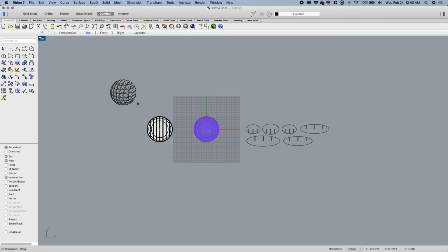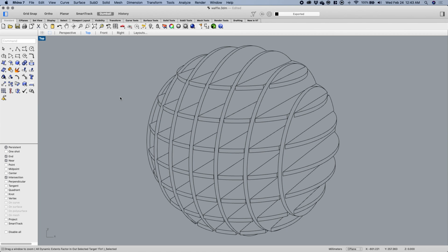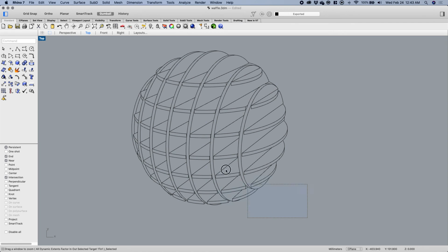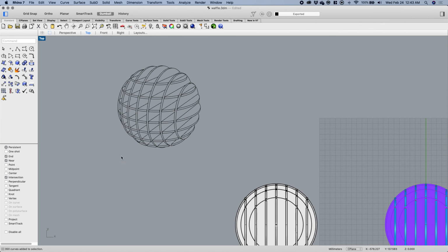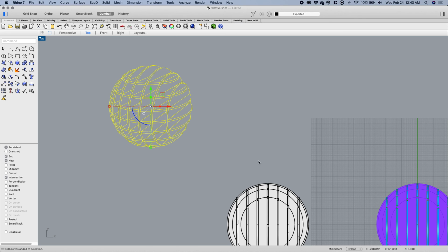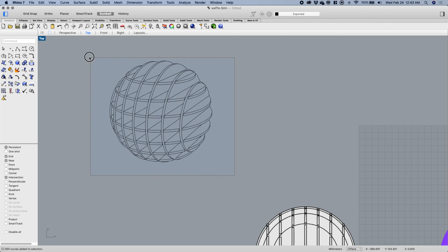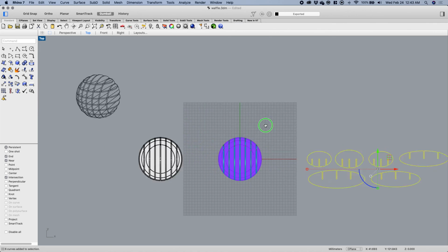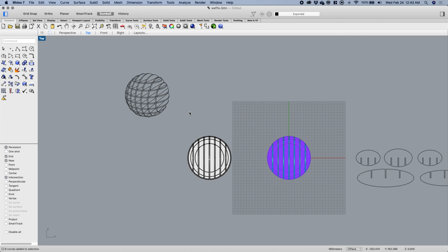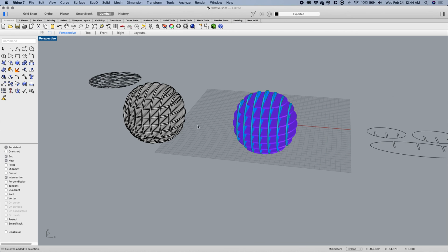So if I go to top now and look over here, I now have a 2D line drawing like this, which I could select these curves and export it as an Illustrator file and sort of compose a 3D-esque line drawing version, along with my flat 2D pieces, if I were to save these ones out as 2D production files. So just a couple ways to visualize the results.